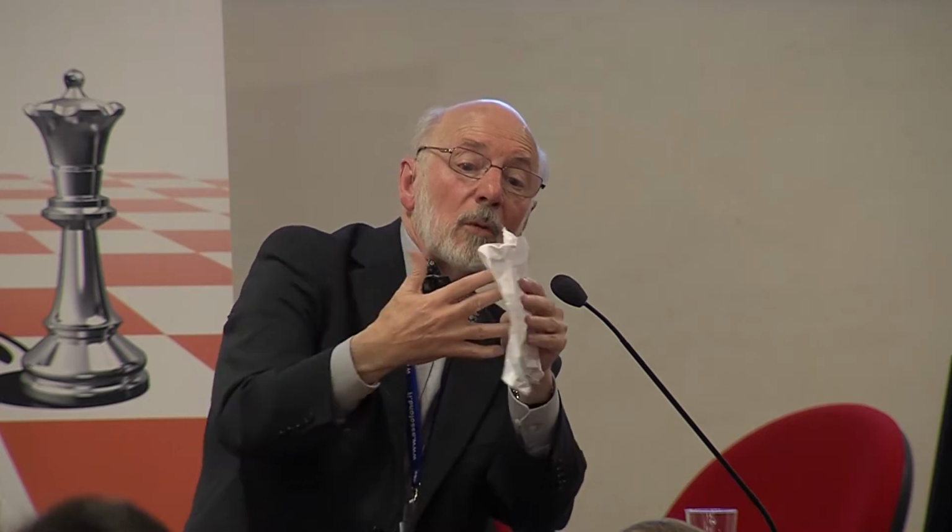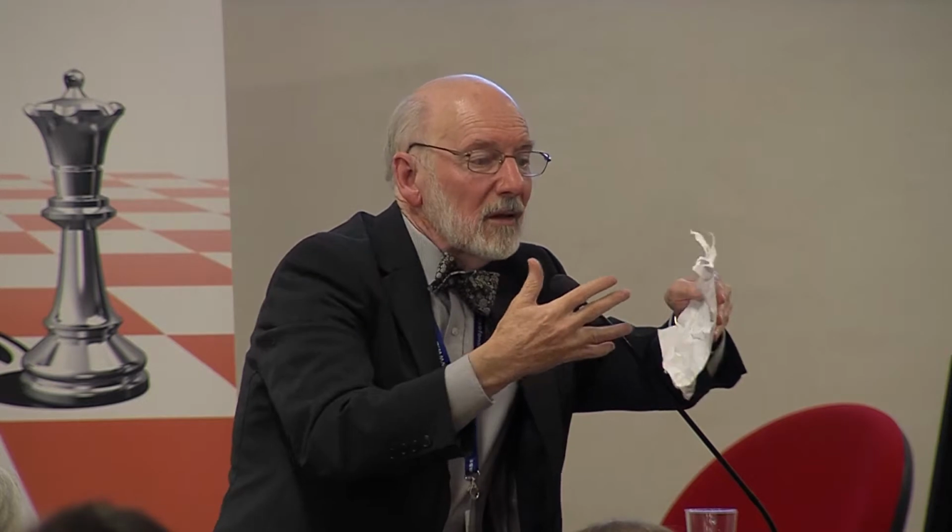These bifilms will very often, not always, but often will be sitting at grain boundaries. That's because a grain will grow and will push, and another grain will grow from this way, and so finally, this becomes the grain boundary. There are still some which are sitting across the grains, but not so many. They're mostly grain boundaries. So whenever I see a precipitate at a grain boundary, I say, it's not sitting on a boundary, it's sitting on a bifilm.